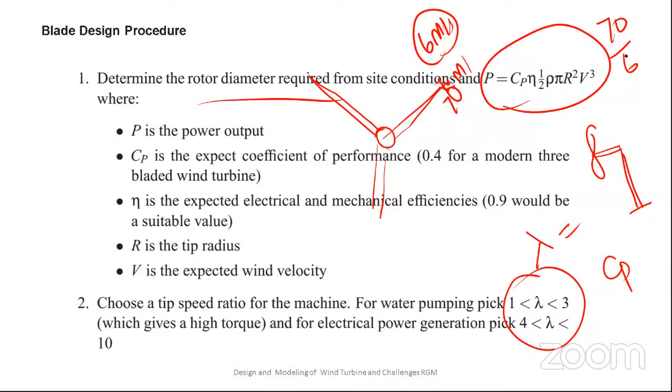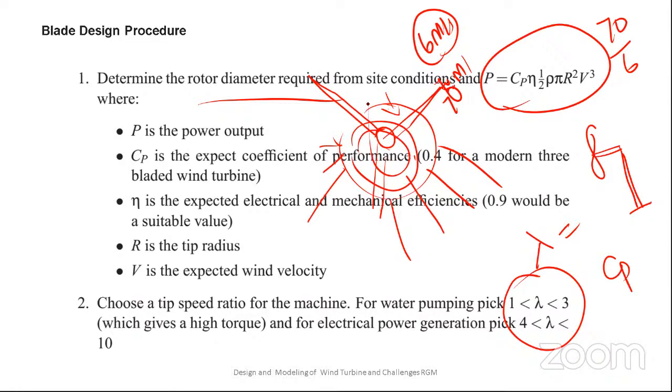The tip speed ratio only will decide your turbine performance. How? Here I say that the wind is blowing. When the rotor rotates very slowly, then all the wind which flows between the blades will not generate any power. In case the rotor rotates very fast, then it will act as a disk. Then turbulent wind will be there, it will not generate any power. So in between you have to decide at what speed it has to rotate.